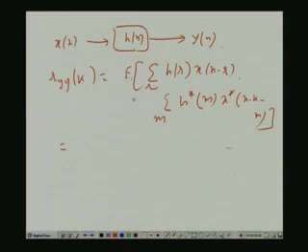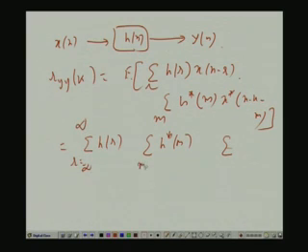And then E will work directly on wherever you have x and x star. So, push E inside using the linearity of E, h r. And then you have E working on this x[n minus r] into x star [n minus k minus m]. Input is WSS. So, this autocorrelation will be a function only of the lag. Lag is what? n minus r minus, within bracket, n minus k minus m, which is r.